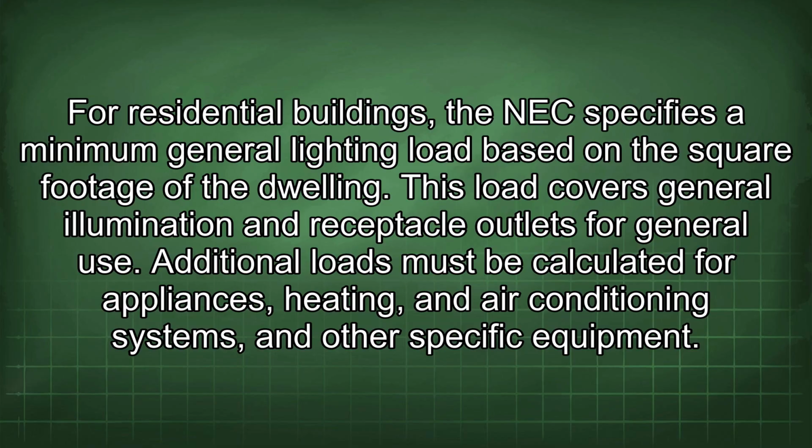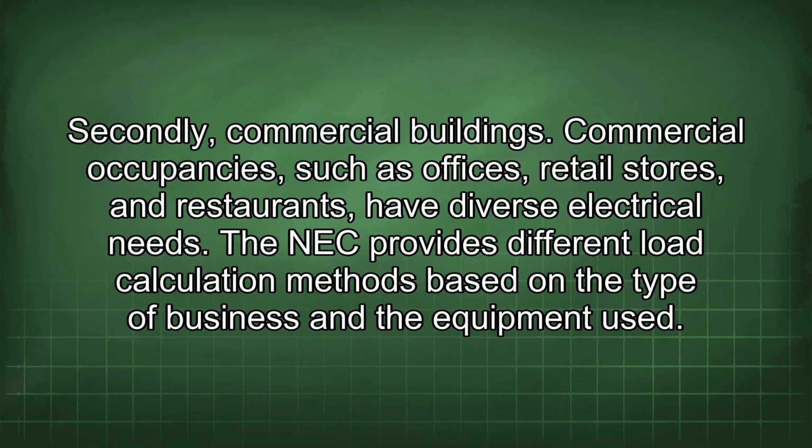Additional loads must be calculated for appliances, heating, and air conditioning systems, and other specific equipment. Secondly, commercial buildings. Commercial occupancies, such as offices, retail stores, and restaurants, have diverse electrical needs. The NEC provides different load calculation methods based on the type of business and the equipment used.